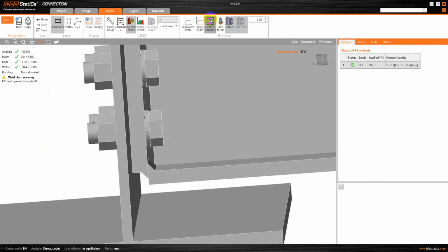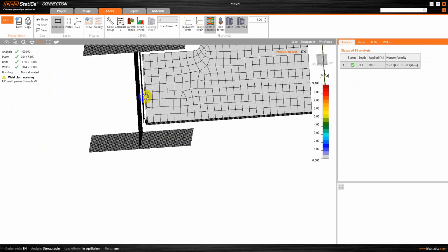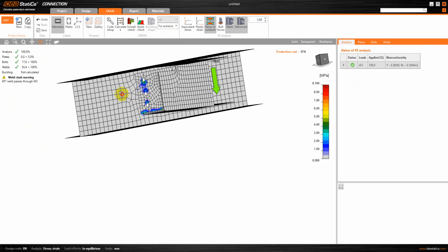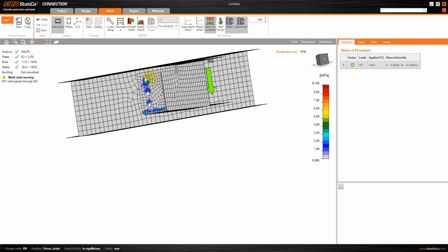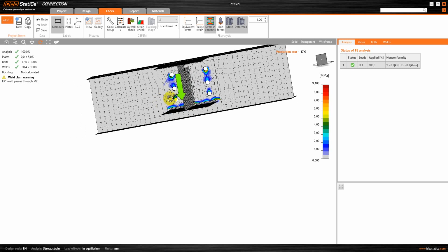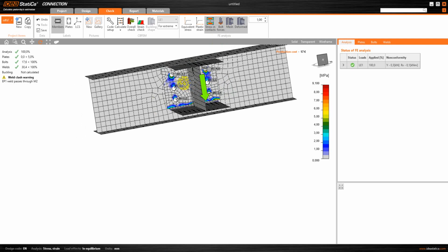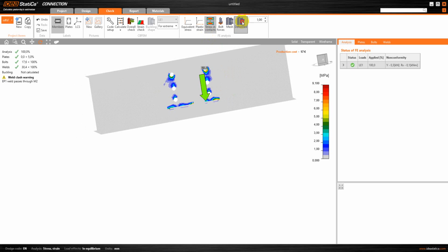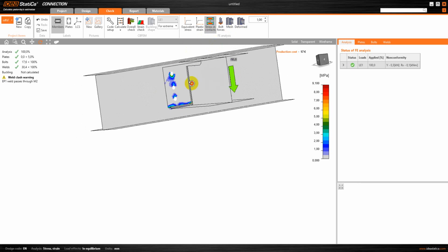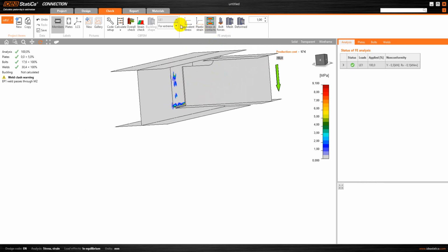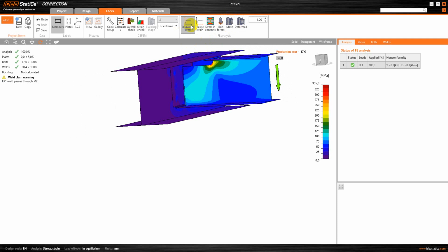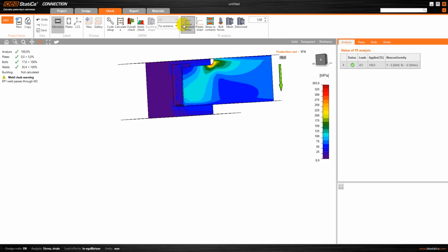From here you can check stress in contact. Where there is a bolt, there is a lot of contact force like this, and you can check the bolt force, 3.224, 2.4, or you can see the deformed shape, equivalent stress, everything.